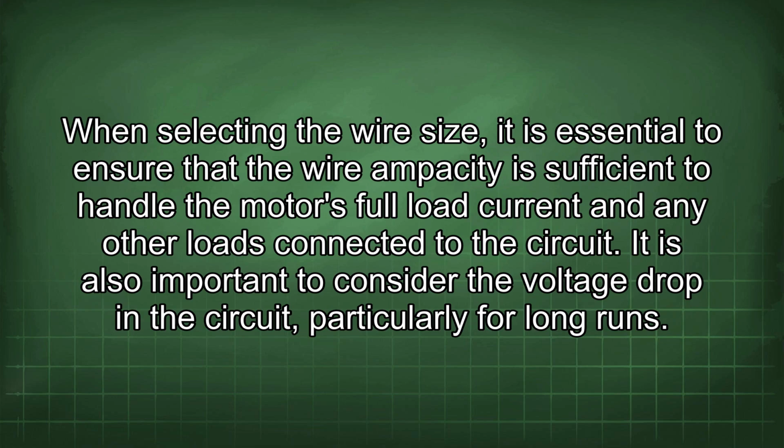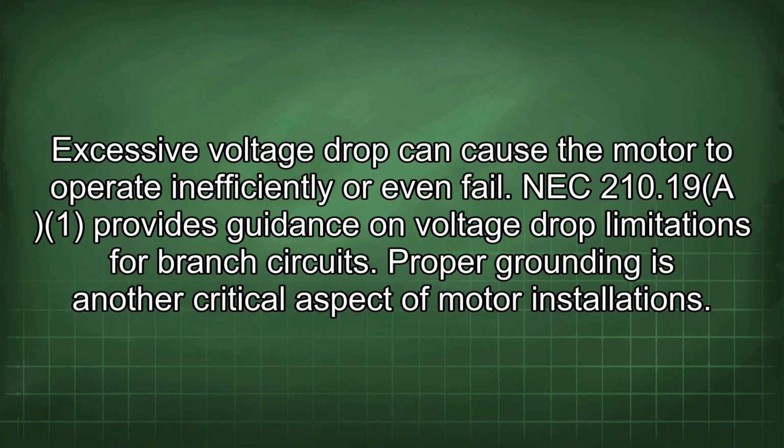When selecting the wire size, it is essential to ensure that the wire ampacity is sufficient to handle the motor's full load current and any other loads connected to the circuit. It is also important to consider the voltage drop in the circuit, particularly for long runs. Excessive voltage drop can cause the motor to operate inefficiently or even fail.